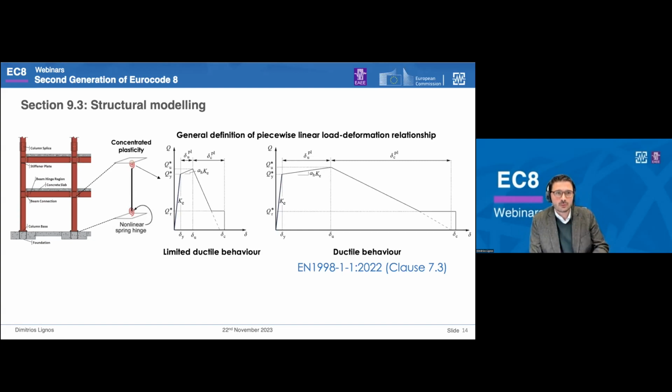Now, one thing I'd like to point out here is that steel, unlike other materials, has a considerable plastic rotation capacity after the peak. This is because the post-buckling behavior of steel elements is quite generous. And here we have provided explicit information on how these rotations can be derived. And if you are doing assessment at near collapse, this could be quite important to consider.